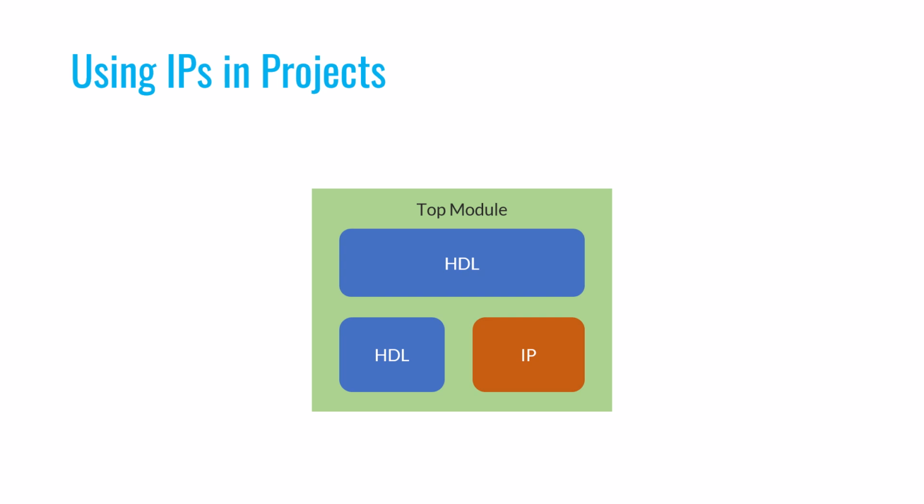Some of these modules, due to their specialized nature, you typically write using a hardware description language like VHDL or Verilog. For others, if a corresponding IP exists, you can use an IP from the ISE software. You bring these submodules together to build your overall system.